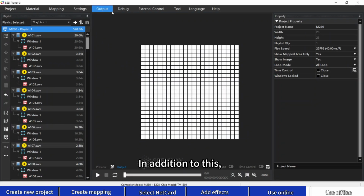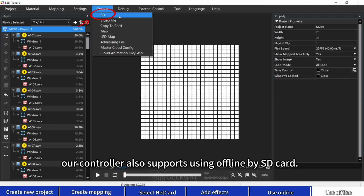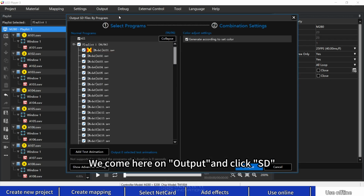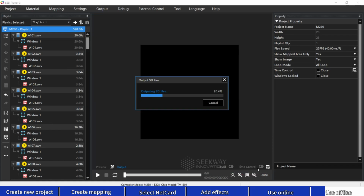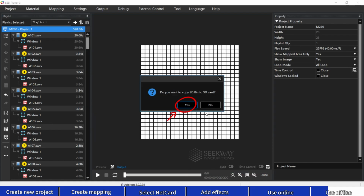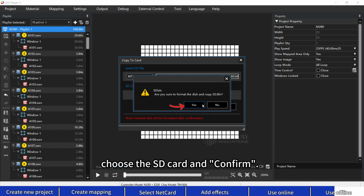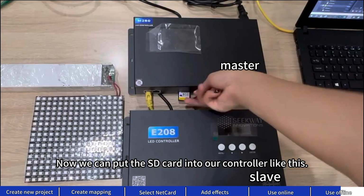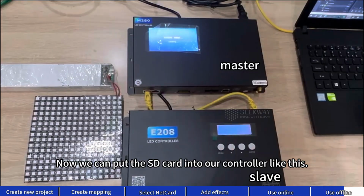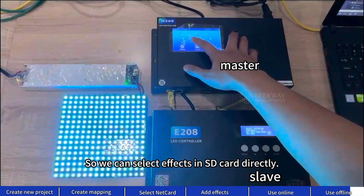In addition to this, our controller also supports using offline by SD card. We come here on Output, click SD. Select the normal programs we need and click Output. When it's finished, we click Yes. Choose the SD card and confirm. And wait until it succeeds. Now we can put the SD card into our controller like this. So we can select effects in SD card directly.